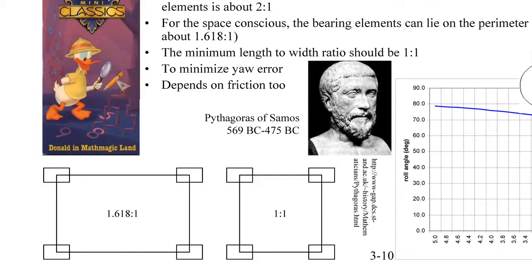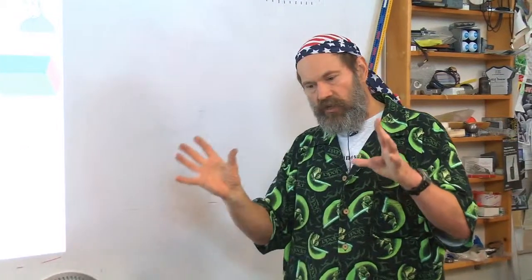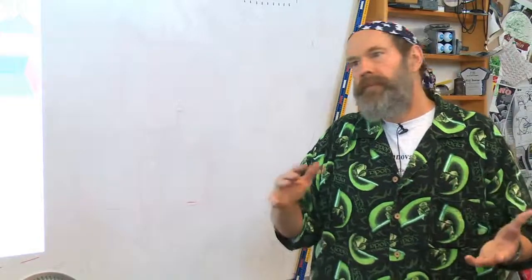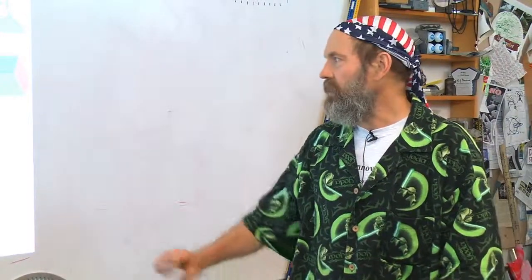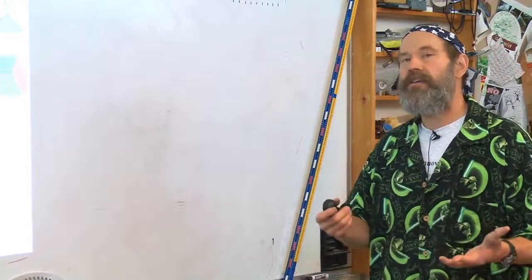Turns out that spacing your bearings about 1.6 to 1 of a characteristic dimension, if it's low friction, is a good spacing for good motions. And when I'm laying out a machine looking at sizes of things, and I'm not even sure exactly what things should be yet, sketching out things initially roughly, I'll pick those kinds of dimensions. It gives me a good starting point from which later on my analysis is likely to show I'm in the neighborhood.